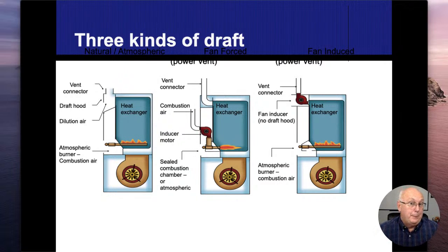And depending on how big that opening is and where that opening is, that may happen after the blower fan is kicked on. It will most likely happen before the blower fan kicks on. But if the blower fan is before the heat exchanger, and that creates a positive pressure on the outside and a positive pressure on the inside, whichever fan is stronger is going to cause the air movement to come in there. But if it's at the very top, sometimes it actually creates a Venturi effect as well.